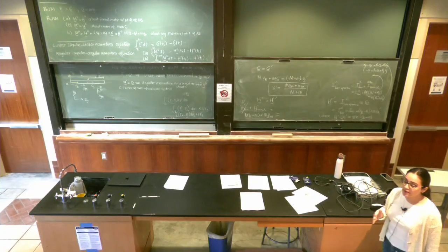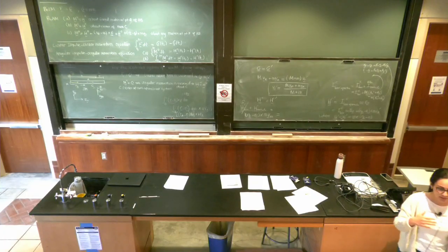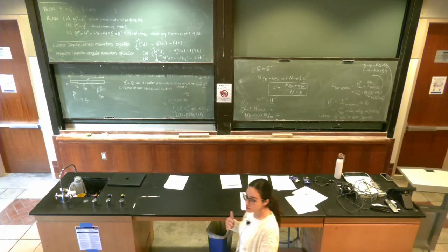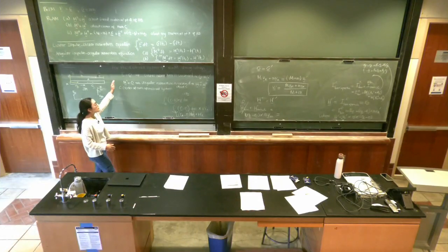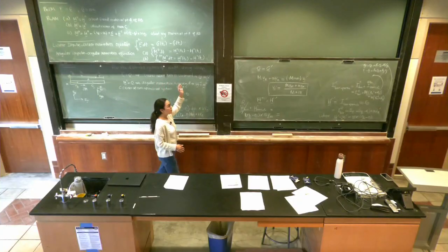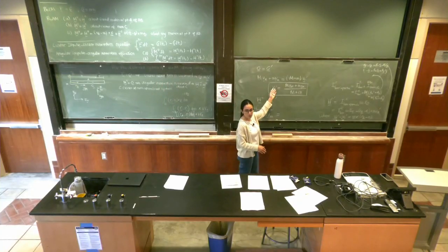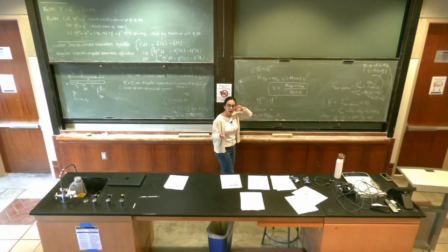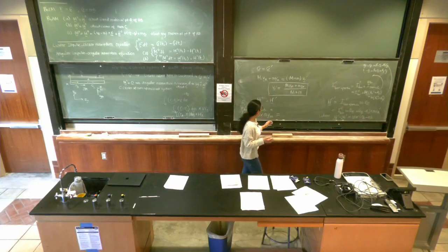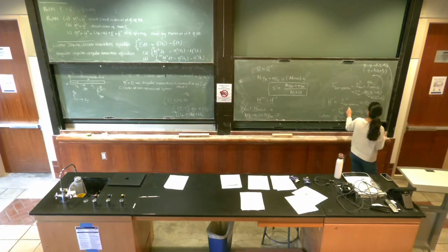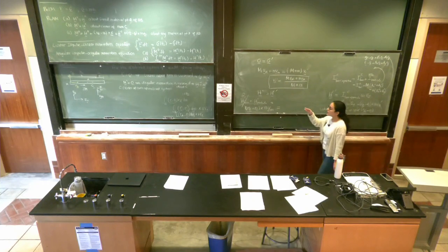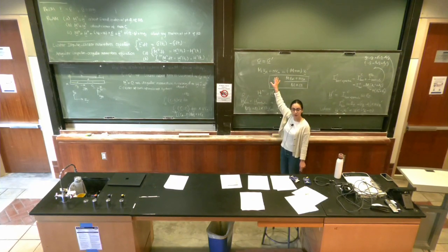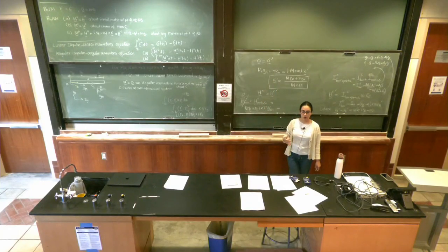Okay, so in summary, we have this. The particle is colliding with the bar. During this collision, we have conservation of linear momentum and conservation of angular momentum. We can use the conservation of linear momentum to determine the post-impact velocity of the bar. And we can use the conservation of angular momentum to determine omega, I will call it omega prime, the angular velocity of the bar post-impact. So the linear impulse-linear momentum equation gives us Vc. The angular impulse-angular momentum equation should give us omega prime.